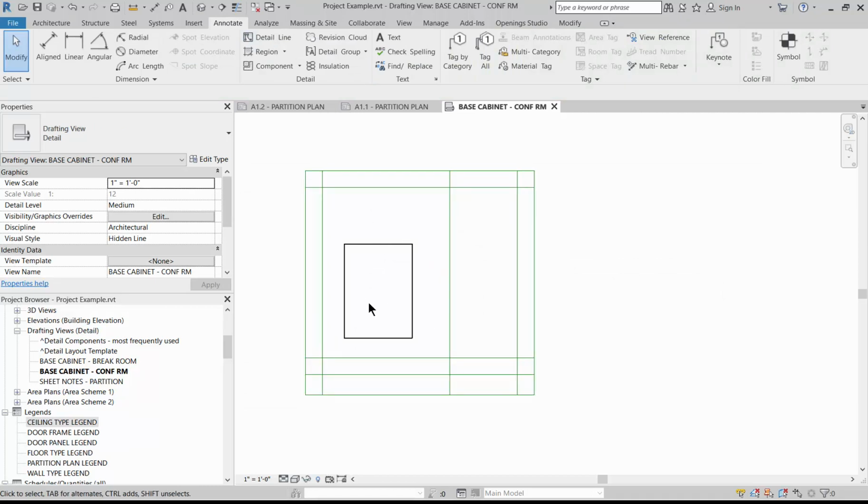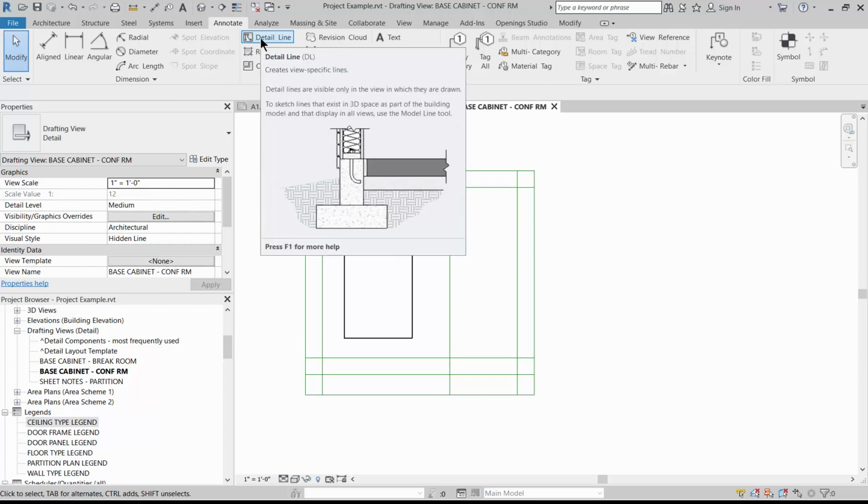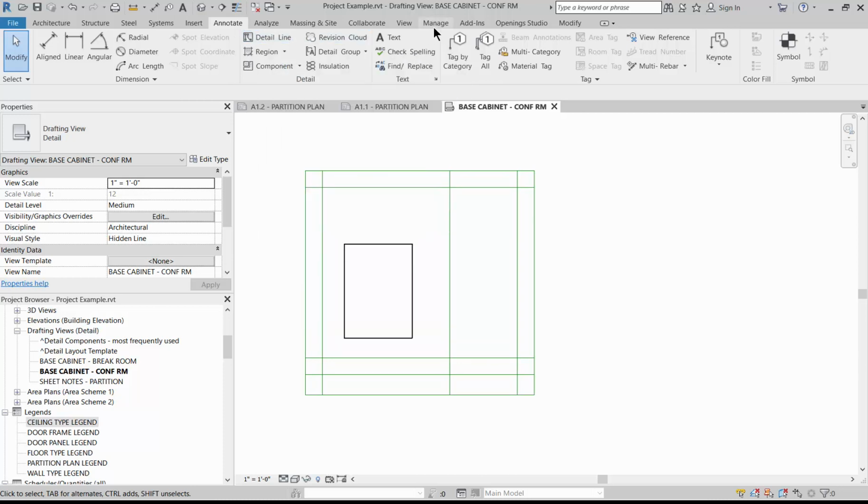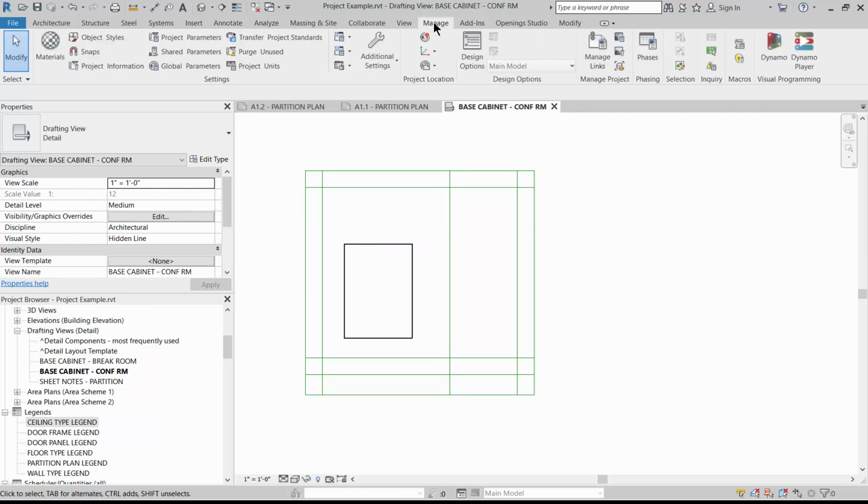Now, aside from detail components, we also use detail lines extensively. And if you wanted to add your own thicknesses, as we do need to abide by the line hierarchy, so the cuts are the thickest lines, hatches and the lines that are further set back are thinnest lines. Thinking back about what we learned about elevations when we did AutoCAD drafting or drafting by hand, it applies to the details. Details are really zoomed in, so the line hierarchy is really important.